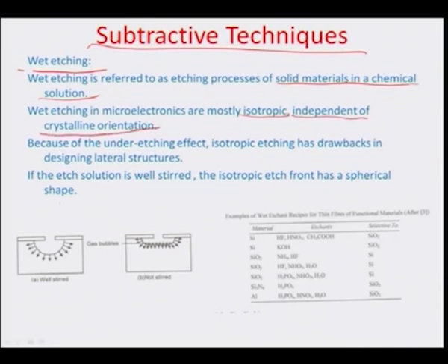So, let us say you are trying to etch this surface of silicon, and you have made a protective layer on the surface, which is not amenable to the etching process, in other words it does not corrode or etch out if you are using a certain etchant. This can form a sacrificial mask on top of the surface, exposing the silicon material underneath in this particular region. The etchant can go and eat away the material, etching in all the directions homogeneously, thus obtaining a hemispherical crater like this.